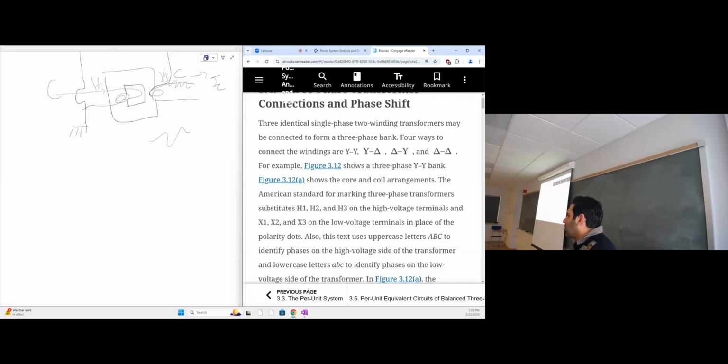So it's not a fault case, but it's not good to have on the system, because let's say our regular systems are either 50 or 60 hertz, but having higher than that frequency could cause problems to our devices. So the delta connected equipment have the ability to restrict or to confine that nonlinearity or the third harmonic within the delta. It will not be getting out of that. So mainly in connections related to generators, let's say, they have that delta connection to make sure all those bad things will remain restricted.